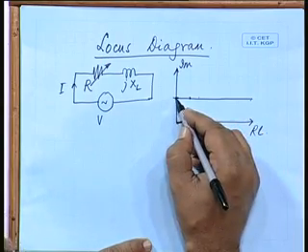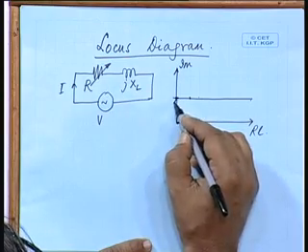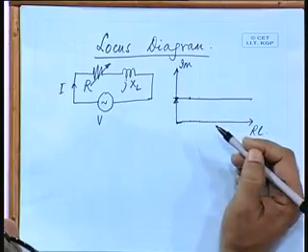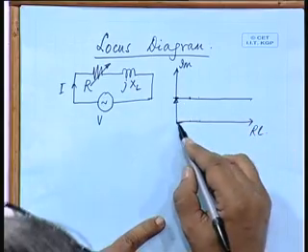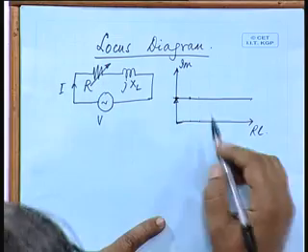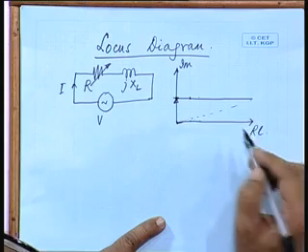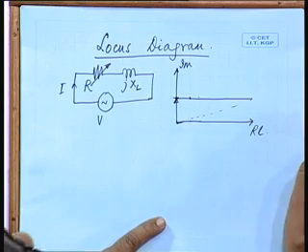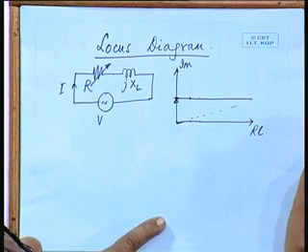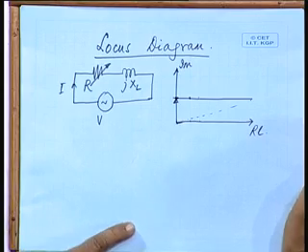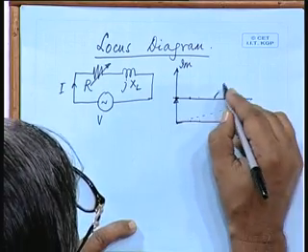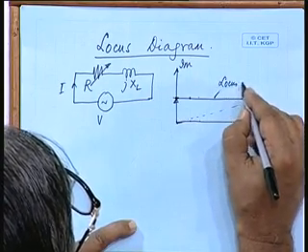It is minimum when it becomes purely inductive. So, that time its value is XL, okay. Resistance is 0 and its maximum value tends to infinity when R is infinity and this angle will tend to 0. So, at a very large value of resistance it will be practically resistive with an infinite magnitude. Okay. So, this is the locus of Z.